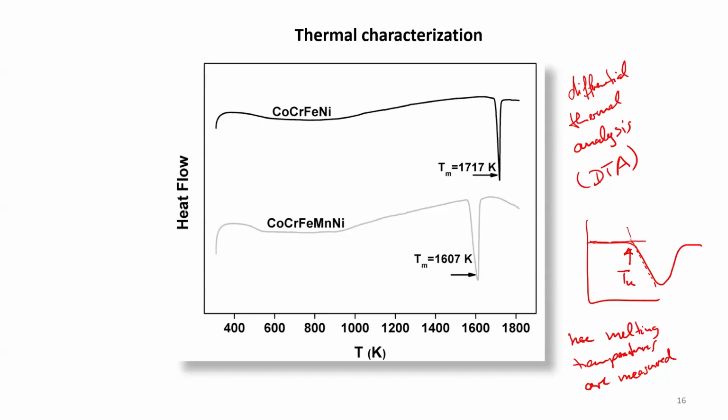So it means if we now compare their diffusivities later on, again, we have to worry how to do the comparison. If we do it just at the same absolute temperature, then we have one measurement done much closer to the melting temperature of the respective material as compared to the other one. Maybe this is not a good comparison. Maybe we should then normalize the temperatures of the measurements for each respective system by the respective melting temperature, and then we can do a good comparison on equal homologous temperatures.